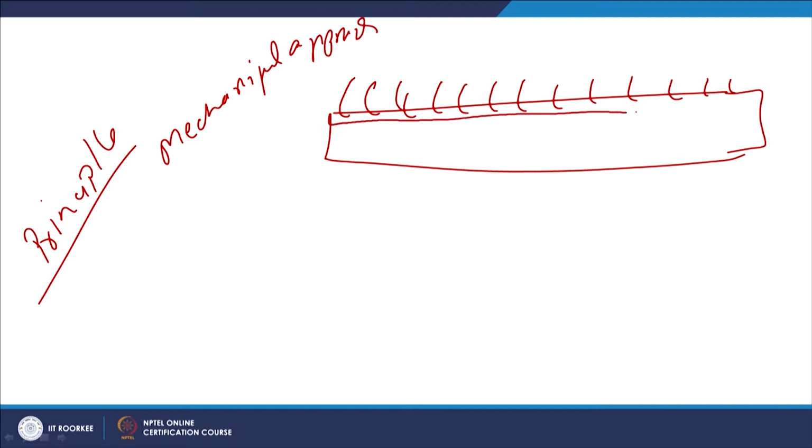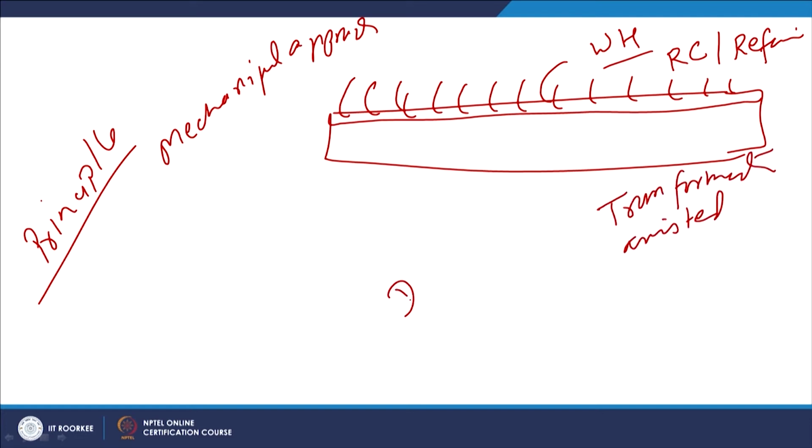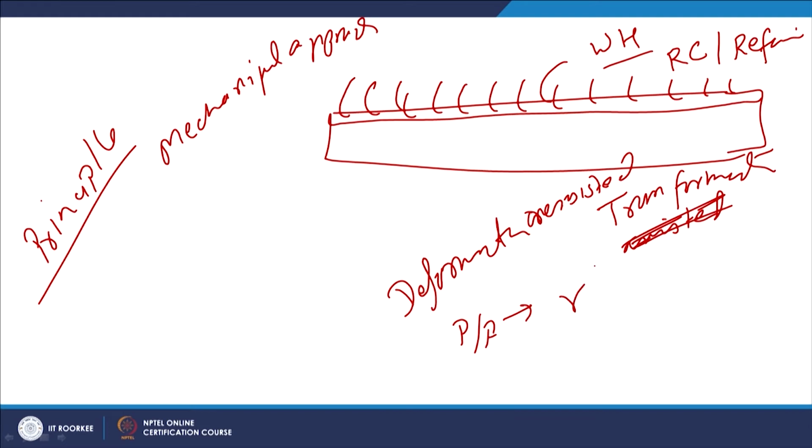This plastic deformation of the surface layers causes work hardening, sometimes recrystallization, grain refinement, and then deformation assisted transformation is achieved. Whenever the material is deformed in a very localized manner, the soft phases like pearlite or ferrite transform due to the heat generation into austenite, followed by transformation into martensite.